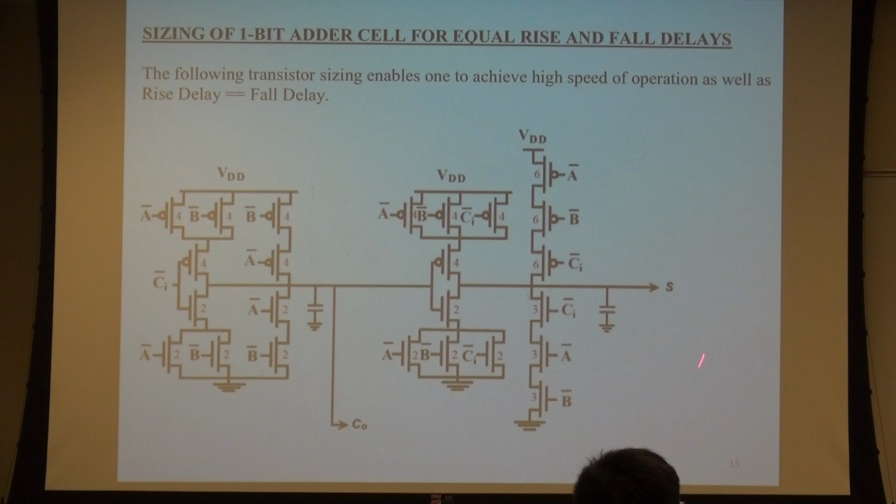Because the speed is not the main factor over here. Speed is most important for these transistors because these transistors will be generating the carry. And this is sum. I give less preference to this particular part of the circuit than this. But within this, these 6 transistors will be sending 6 patterns, and these 4 transistors will be responsible for 2 patterns.